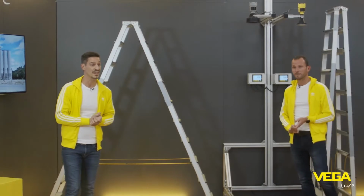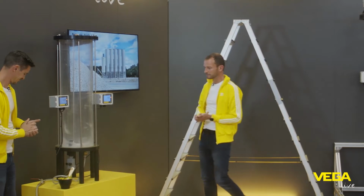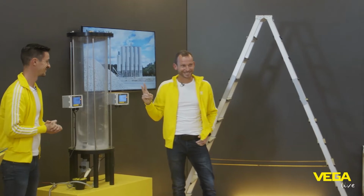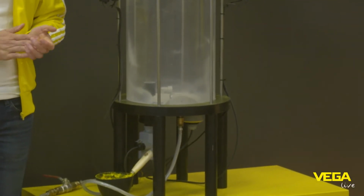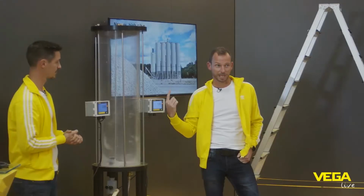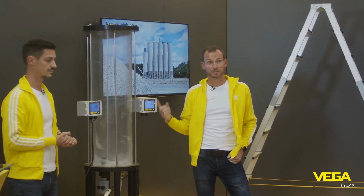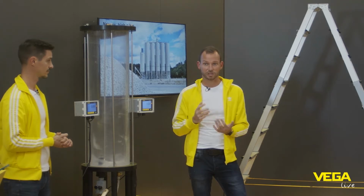For this, we have prepared the next live demonstration model. Over here, we have a tank or a vessel. And here we have installed two level sensors, but not on the top over here, they are installed below. So we are measuring now from the bottom to the top, upside down. You should not install an ultrasonic or a radar device on the bottom. You should always install them on the top of the vessel. But in this live demonstration, it is better to show and to explain.